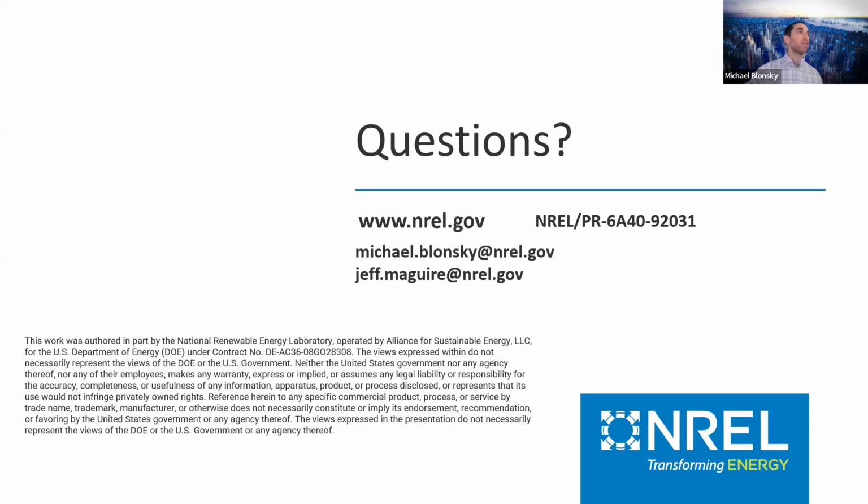How can we introduce inverter-based resources, such as injecting reactive power from a household with an EV or battery? This is a good question. So currently, we enable reactive power. We have power factor inputs for different devices, and we can set reactive power for solar. As of now, we do not have the ability to set reactive power from an EV charger or from a battery. That has been of interest, but it just hasn't been high enough priority for us to incorporate it in the model yet. But it would be fairly simple.